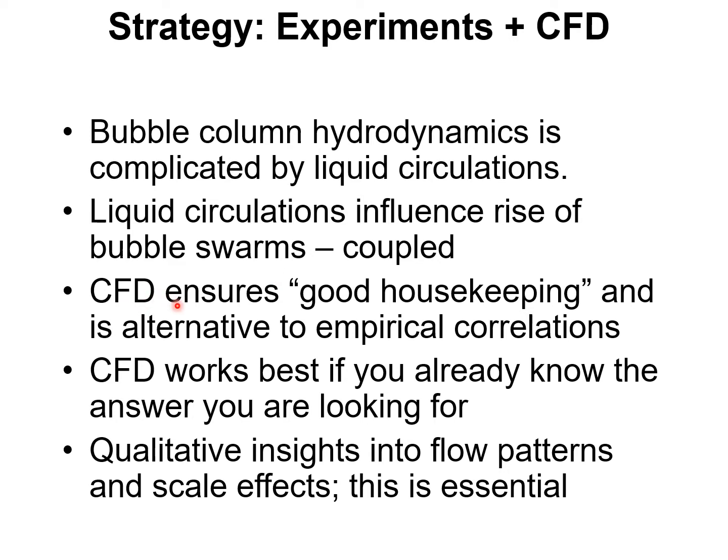Computational fluid dynamics ensures good housekeeping and is a viable alternative to empirical correlations for scaling up. Indeed, I would even argue that empirical correlations for scaling up bubble column slurry reactors are not to be recommended, and CFD is perhaps the only route to reactor scale-up.